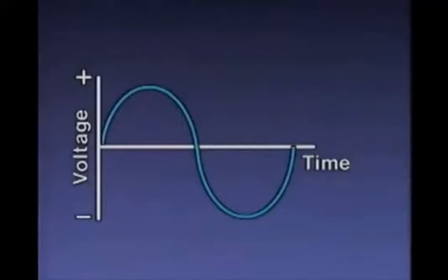The value of the induced voltage is at a peak 2 times during each cycle. Since the value of the voltage is continually changing, the peak voltage value is not the true or effective value of the voltage that's produced during the cycle. Instead, the effective voltage is an average value. In most cases, the average that's used is called the root mean square, or RMS value.